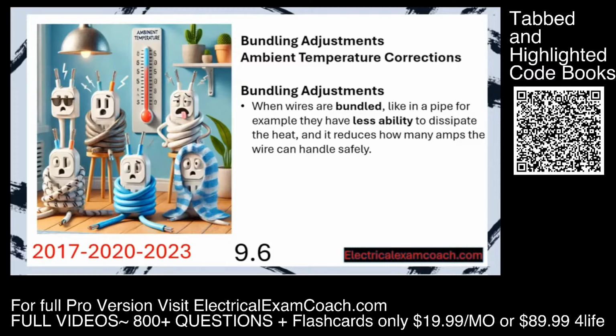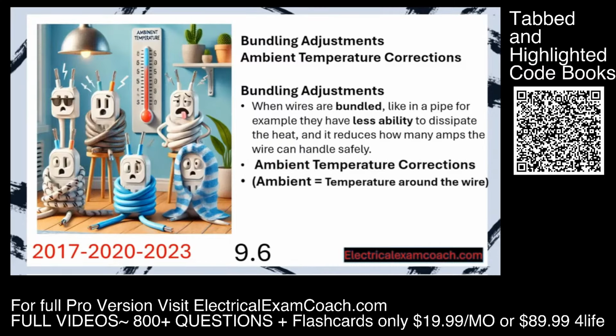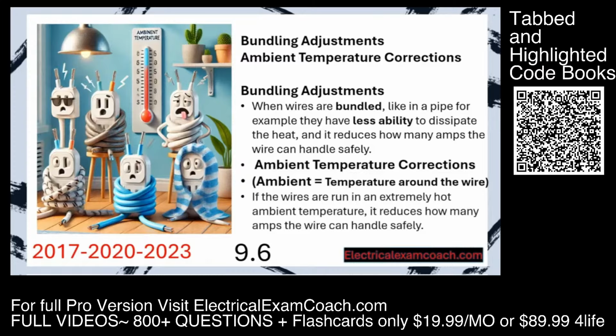It's very similar. We just pull from a different table, but it's the same style demand factor process that we've been doing this entire program. Ambient temperature corrections are like this. If wires are run in an extremely hot ambient temperature, it reduces how many amps the wire can handle safely. And let's not forget the basic definition of ampacity. It's how many amps the wire can handle safely under its conditions of use.